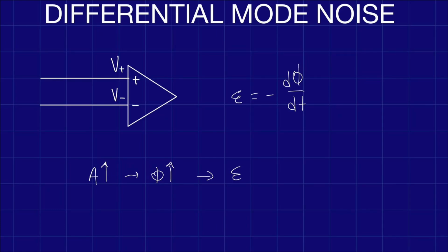And we'll call the electromotive force just the induced voltage, because that's what it actually is at the end of the day. If you would like to watch a video also on Faraday's law and Lenz's law, where I explain how exactly the external field will influence the circuit, click on the top right on this video and get back to this video afterwards. So here the first fix that we can do is put these 2 cables as close as we can to each other, as close as possible, so we minimize the distance, so we minimize this disturbance.